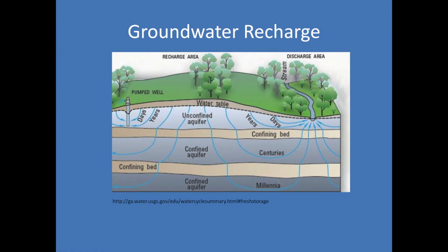Okay, so when we talk about groundwater recharge, this slide demonstrates what I was talking about earlier, where the unconfined aquifers often have a quicker recharge to the surface hydrology, in this diagram, the stream. If you notice where the day marker is, if a pollutant was spilled on the surface there, it could reach that stream within a couple days. The further you are away from your surface hydrology, the longer it would take. But you could see some of the confined aquifers that are much deeper, chemicals that migrate and infiltrate much deeper down sometimes take centuries to millennia to actually reach that surface hydrology. And in this case, our geology is flat, but if you could imagine these geology layers at a certain dip, that would mean that the contaminants could be flowing for an even longer period of time along those geologic strata along the dip.